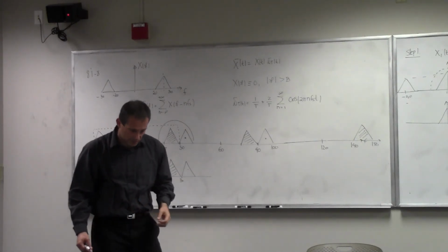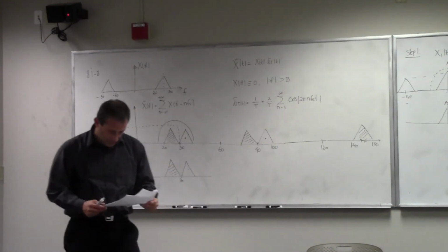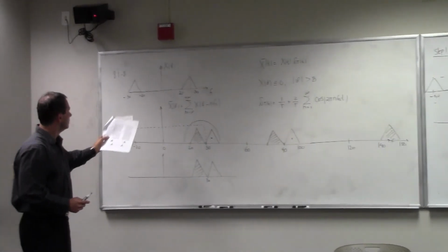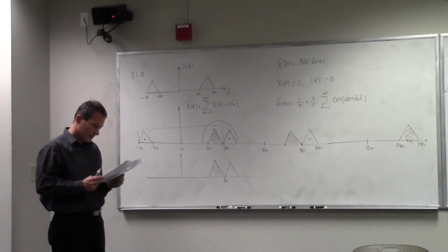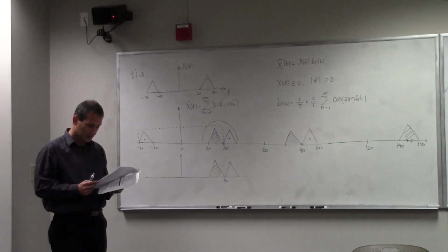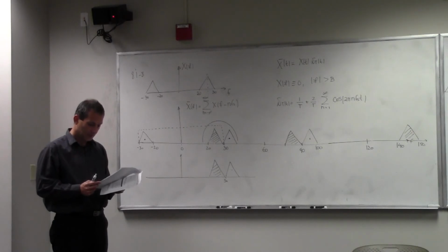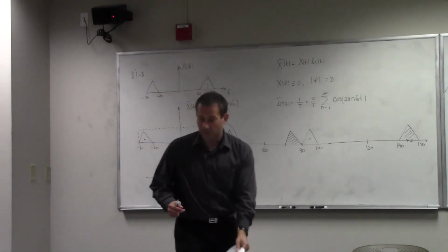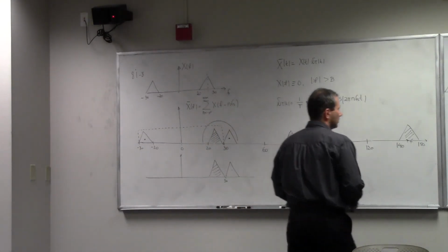Okay. Anything else in this problem? Let me see, there's a certain busy student who looks at this signal here and concludes that its bandwidth is really 100 Hertz and decides that the sampling rate of 20 Hertz is adequate for sampling x of t. Sketch the spectrum of the signal sampled at a rate of 20 Hertz. Can she reconstruct x of t from these samples? That's a very cool question, so let's see. Maybe she can.